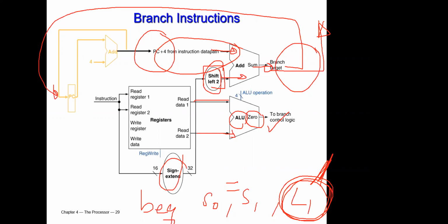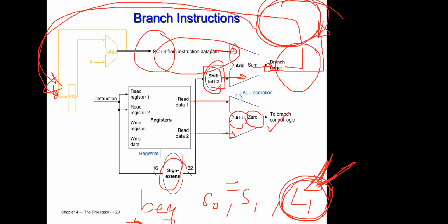But what happens if they are not equal? Do I have to go to that particular address? What will be the next instruction to be executed? Just the following one, which means program counter plus 4. Yes, that's why, as we will see later on, we will add a logic here before we actually update this. As you can see, we are building the blocks step by step to satisfy what we knew in advance as a required task.